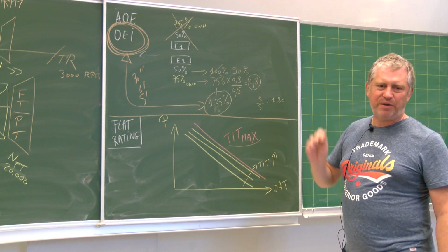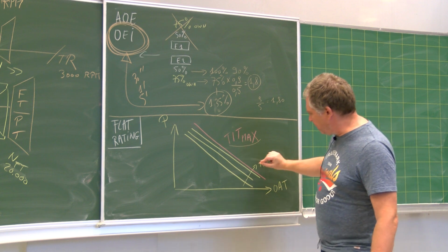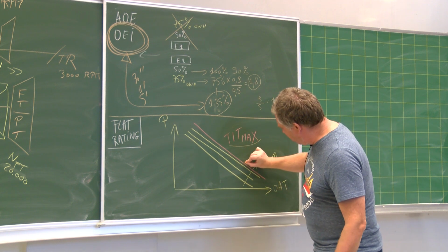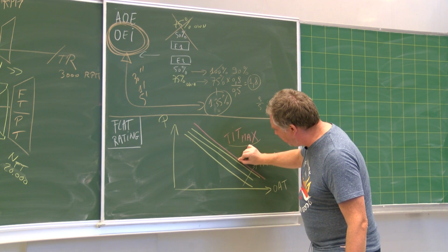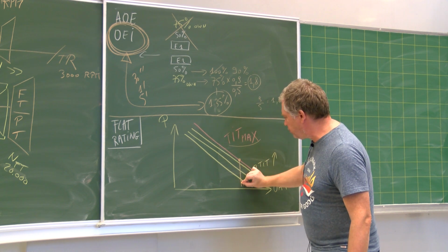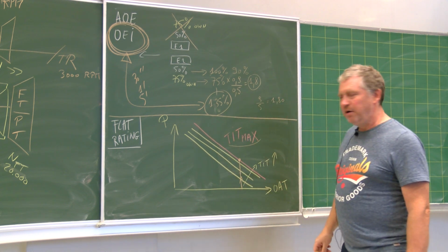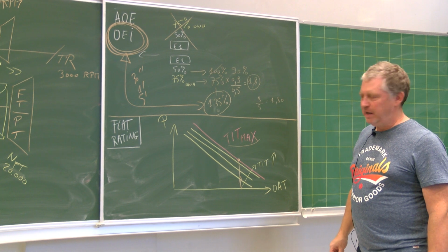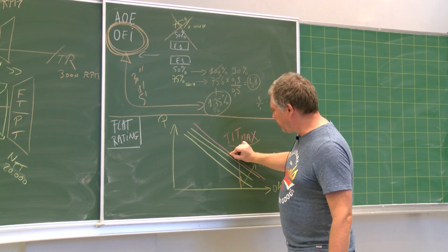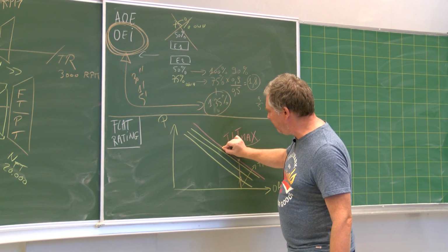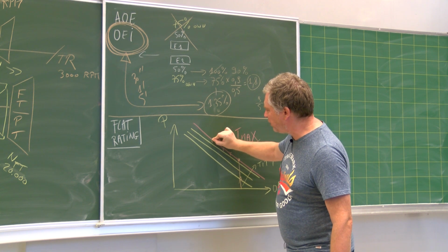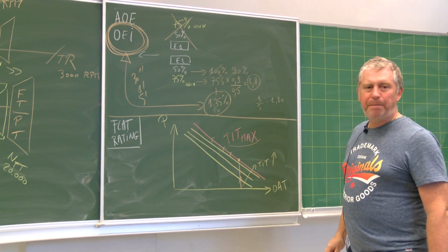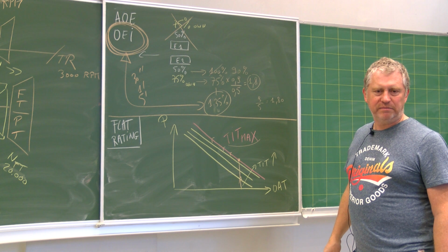Temperature is decreasing. What's happening? The pilot is here, for example, at the beginning. So high outside air temperature. And what's happening with the decrease of the temperature, not changing the TIT, is that the power is increasing.